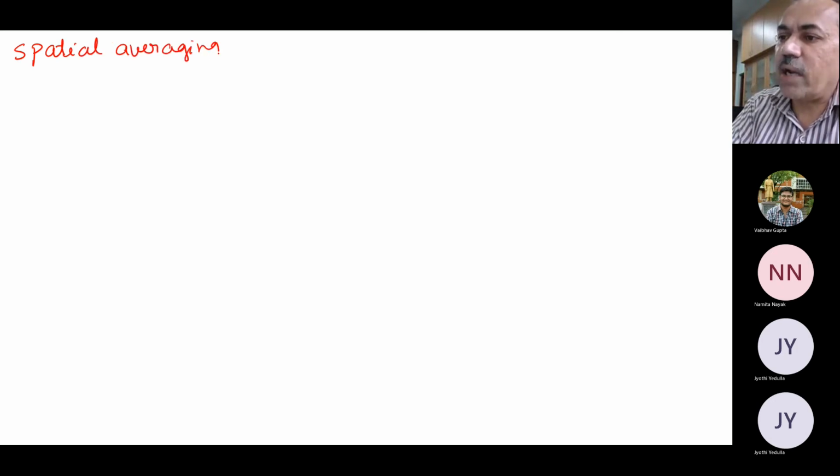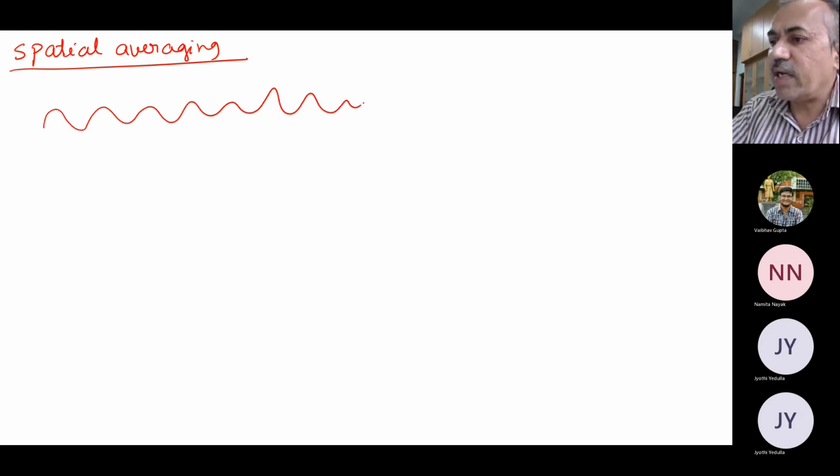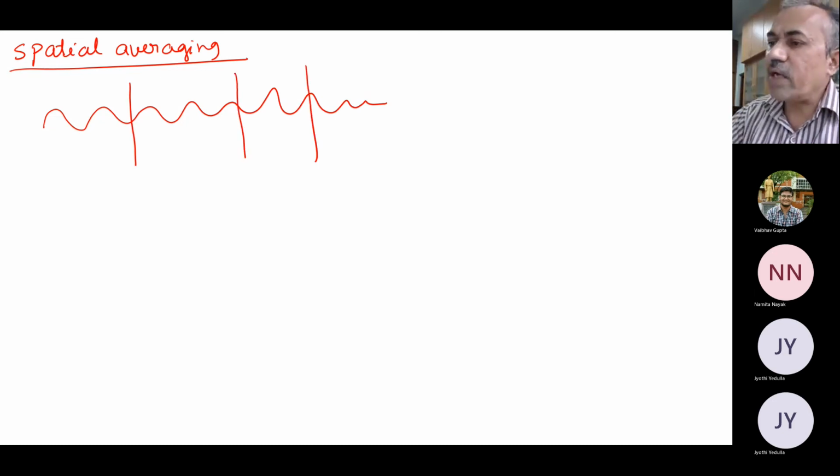Okay, so this is another method. What we try to do is, the Young's modulus is a random field, something that is varying. Now you divide this into pieces. In the previous method we were taking only a particular value here. In this method you do an average actually. So E1 is 1 by L by 4, integrated from 0 to L by 4.